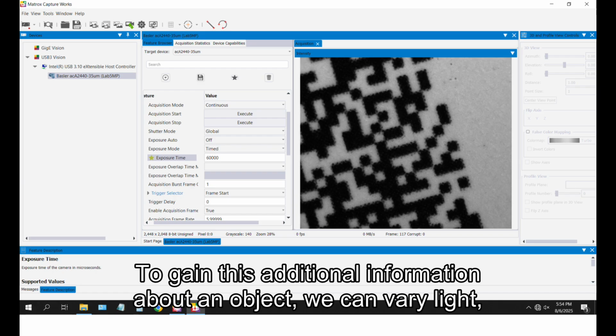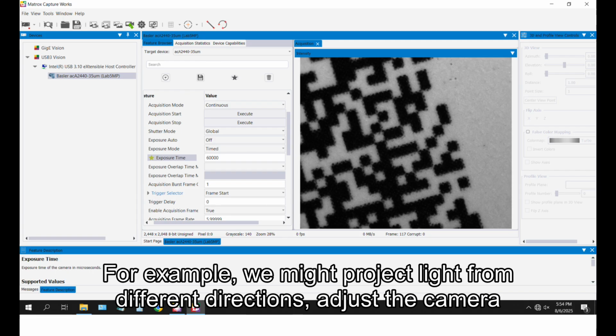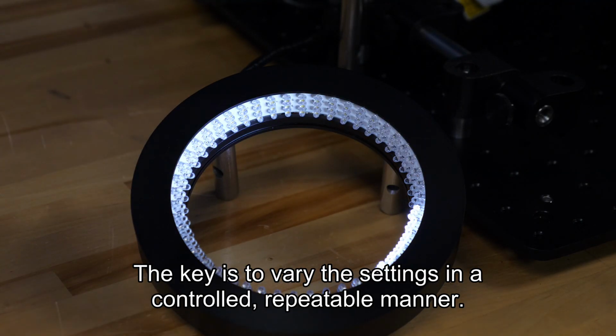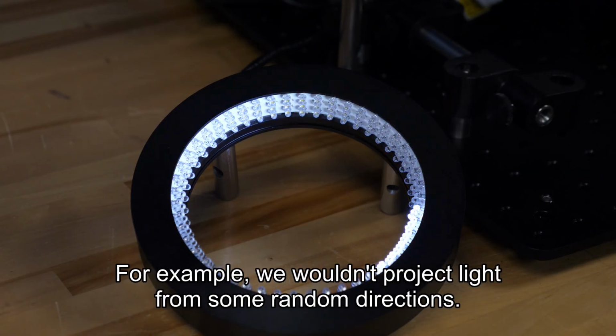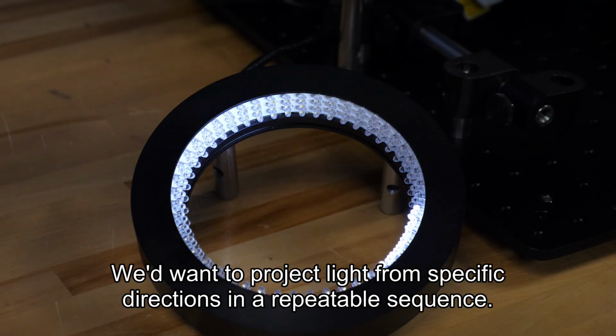To gain this additional information about an object, we can vary light, camera, and lens settings. For example, we might project light from different directions, adjust the camera exposure duration, and/or tweak the lens's focus. The key is to vary the settings in a controlled, repeatable manner. For example, we wouldn't project light from some random directions. We would want to project light from specific directions in a repeatable sequence.